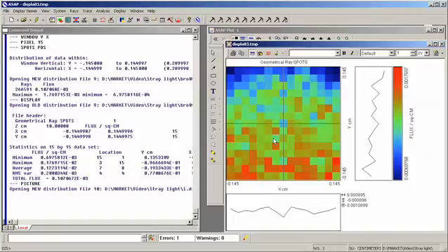Now this is our final answer, but for stray light calculations that's not enough. We need to know not only what is the stray light irradiance, but which contributors to the stray light irradiance are the larger of the two. Is it the interconical baffle or is it the primary mirror? When ASAP is doing the ray trace, it is keeping a partial history of that ray trace that includes most of the information about where the stray light is coming from.